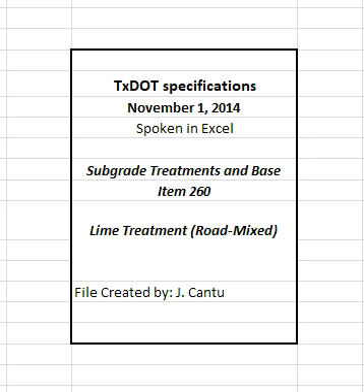5.1.3 Quick lime. 5.1.3.1 Dry. Lime will be measured by the ton, dry weight, of the quick lime. 5.1.3.2 Slurry. Lime slurry will be measured by the ton, dry weight, of the quick lime used to prepare the slurry multiplied by a conversion factor of 1.28 to give the quantity of equivalent hydrated lime, which will be the basis of payment.